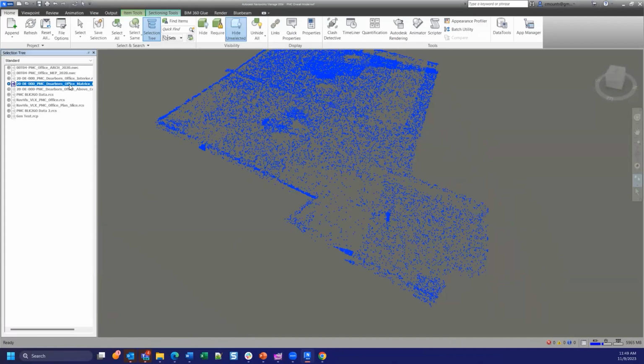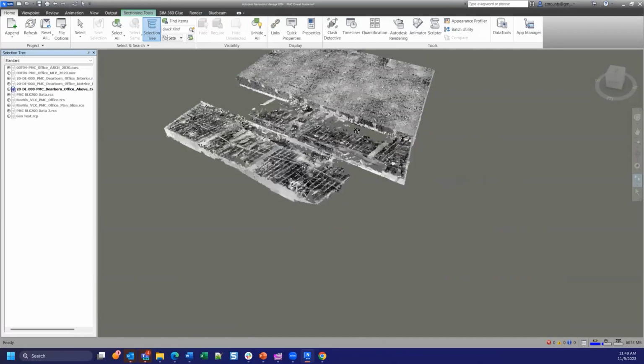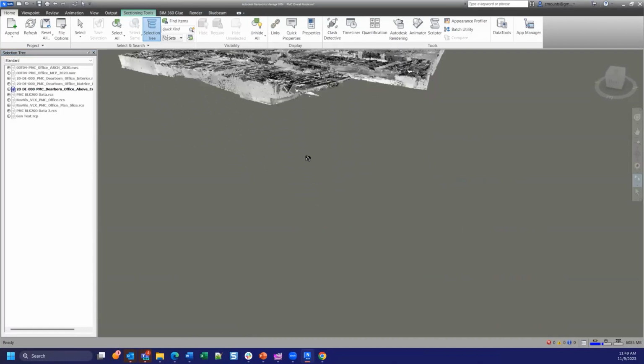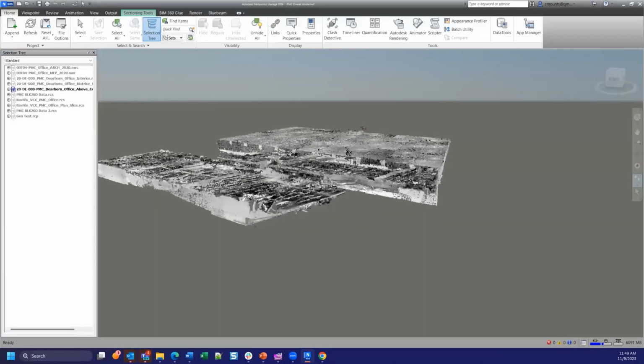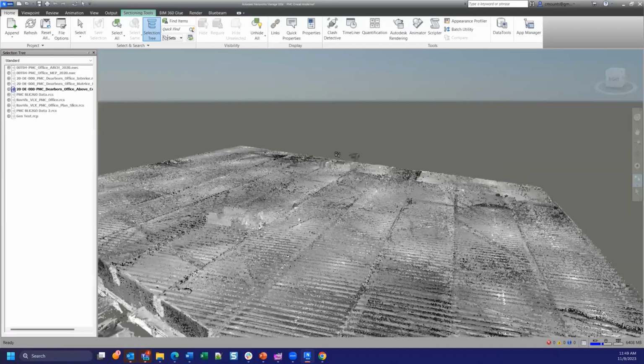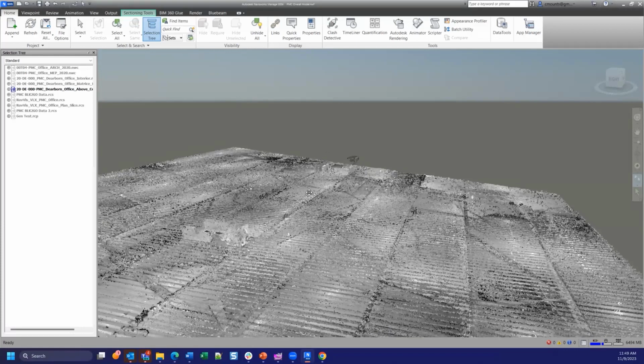Okay. One last thing that we haven't touched on yet that is important to a lot of people is scanning above active ceiling systems or drop ceiling systems. Right now, the only way that I would recommend doing this work is with tripod-based scanners. And so you can combine the tripod above ceiling with the mobile units below to sort of maximize efficiencies there.